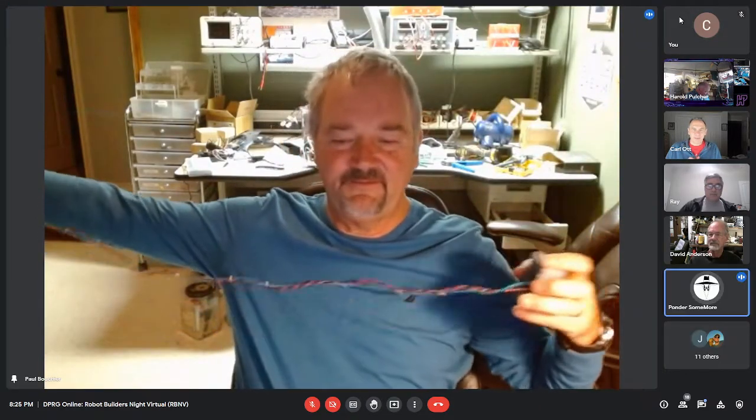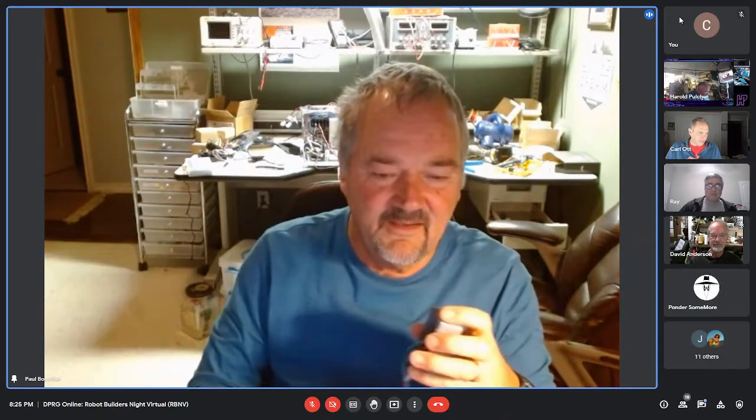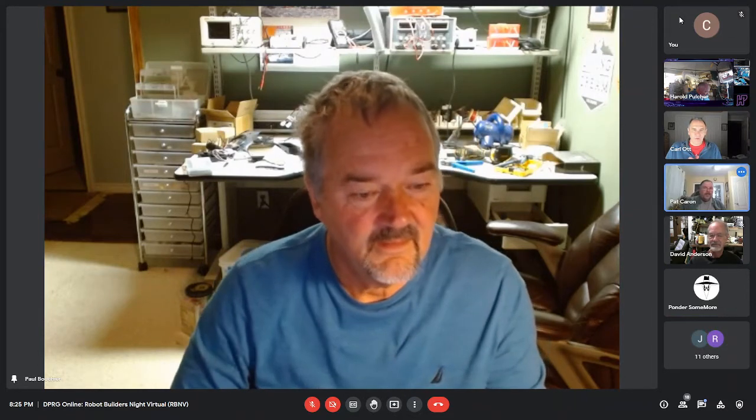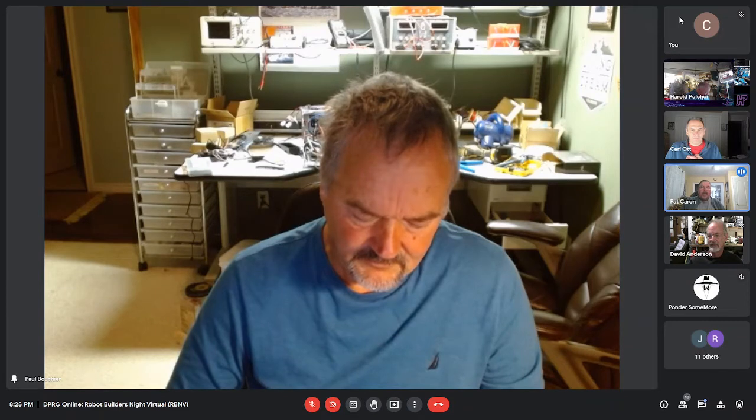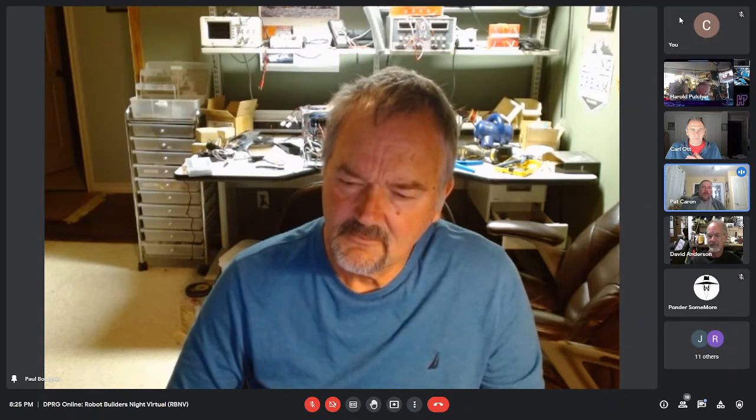Keep it well under a meter. A meter and a half, maybe. I would keep it under a meter. Use shielded wire as tiny as you can get. Oh, really? Yeah, because it'll give you less capacitance on your wires, and that'll help your communication speed. What do you mean, shielded or twisted pair? Twisted shielded, but the smaller you can get, like 24 gauge or smaller, 30 gauge, that'll help with your communication speed if you're going with a long wire.